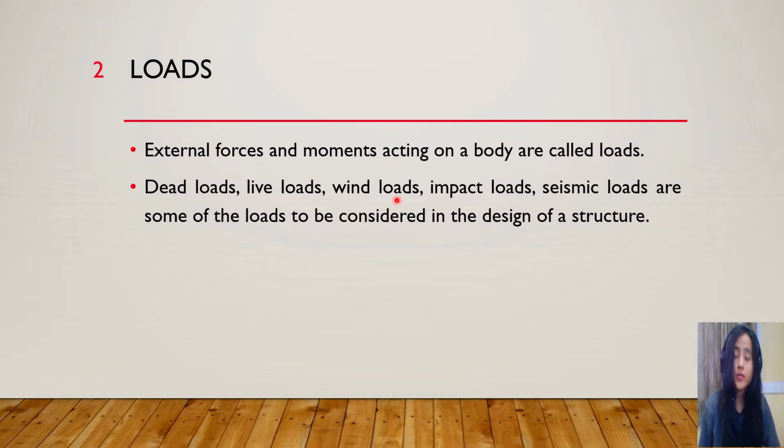So next one is wind loads. This wind load primarily acts horizontally. So these are horizontal loads caused by the movement of air relative to earth. Okay, so wind load is required to be considered in a structural design, especially when the height of the building exceeds 2 times the dimension transverse to the exposed wind surface.